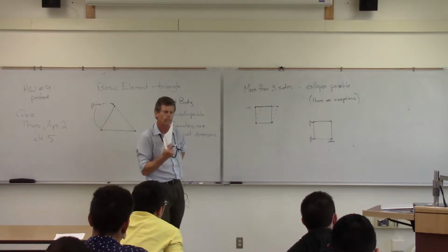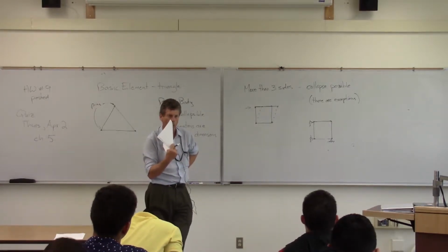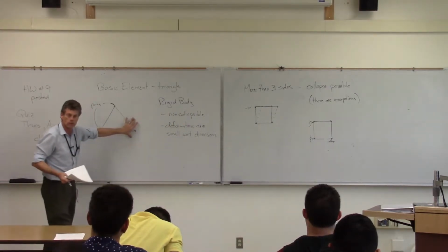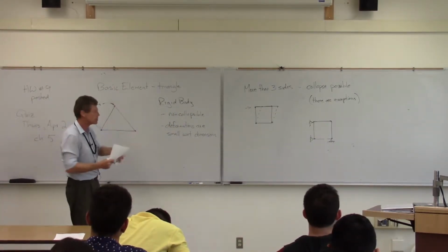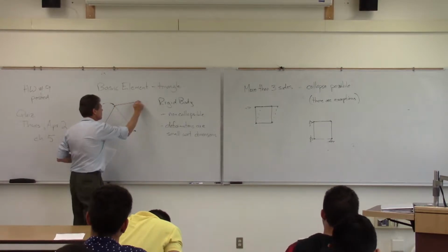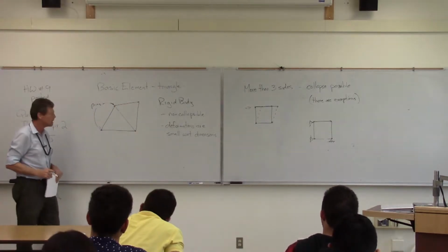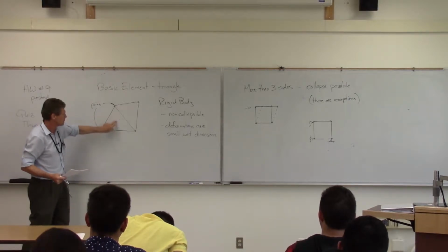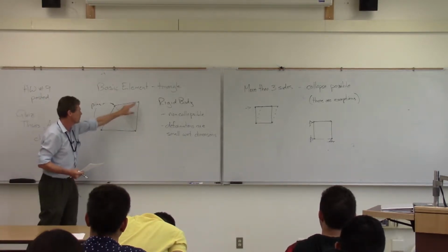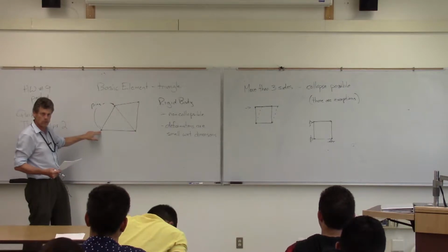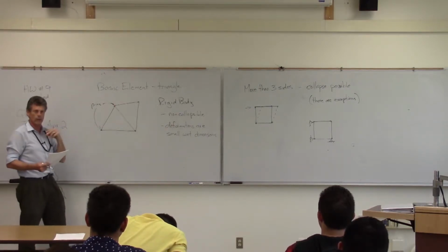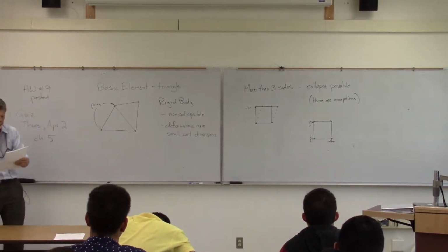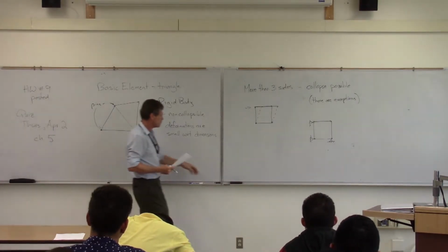Question? What if you put two triangles together? Would that be possible? Yes. Well, matter of fact, that's how we're going to build trusses, basically. It's just going to be a combination of triangles. We're just going to keep going like so, like that. Yeah. Think about it. It's another triangle, so it's rigid. They're connected together now, so when I pull on that, if this end's restrained, then it's not going to go anywhere. So good thought. Yes. That's how we're going to construct those, basically. We're going to follow through with that.